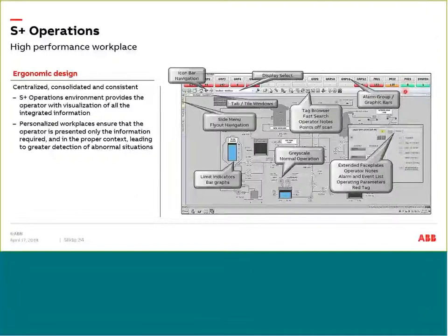So if you see here, the second one, I have 5 and it's still green. That means I have the lowest priority alarm in that alarm group. I have orange showing that, okay, I have a priority 2 alarm, which is the highest one in that group. And on the left one, I have red. That means I have priority 1 alarm in that alarm group.